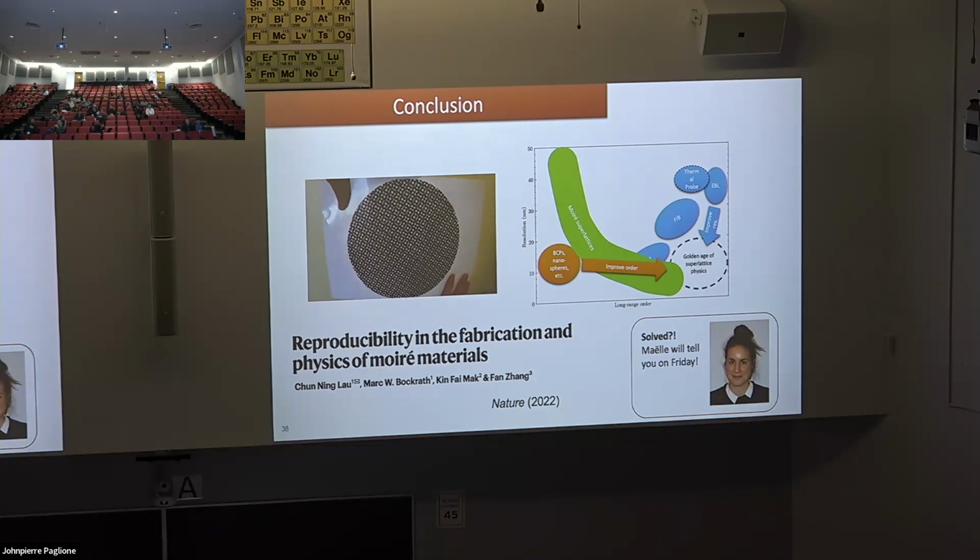Yeah, and then AFM, what mode are you operating the AFM in? So this is contact mode. It does a double pass. It does one pass in tapping mode for topography, and then it goes in contact mode and turns the heating on and off where it needs to do some kind of an indent. Okay, so do you ever have issues with building up material on the tip? Because even in normal tapping mode, you can get material building up on the AFM tip.